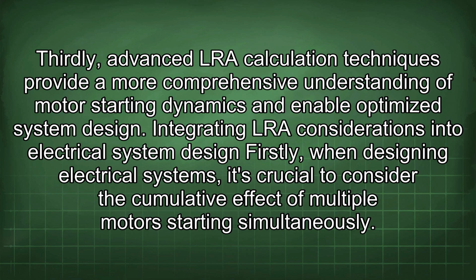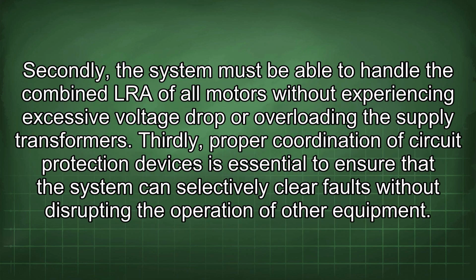Integrating LRA considerations into the electrical system design. Firstly, when designing electrical systems, it's crucial to consider the cumulative effect of multiple motors starting simultaneously. Secondly, the system must be able to handle the combined LRA of all motors without experiencing excessive voltage drop or overloading the supply transformers. Thirdly, proper coordination of circuit protection devices is essential to ensure that the system can selectively clear faults without disrupting the operation of other equipment.